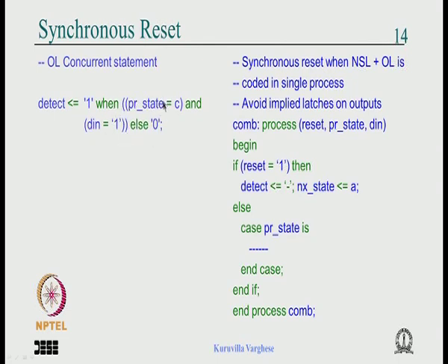But again it is tough with an enumerated data type, because here we are using a symbolic assignment, and here it's a numerical value, and though ultimately it will all be converted to standard logic vector, it is difficult at least to do the with select. So no harm, because you are specifying both mutually exclusive conditions, so there won't be any priority, and this will result in a simple logic.